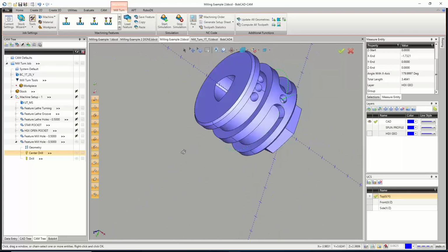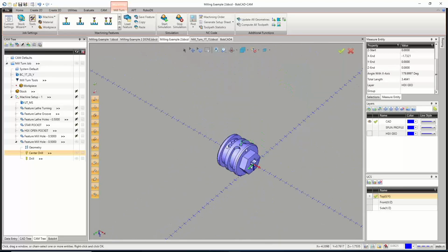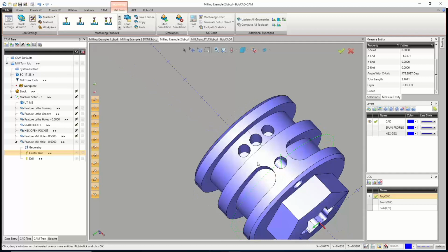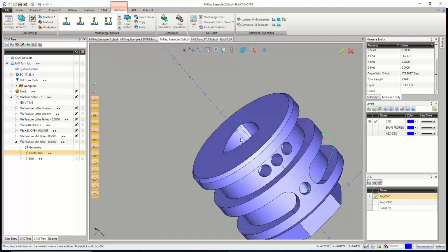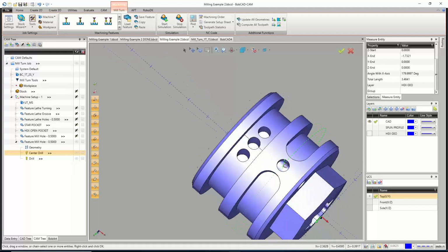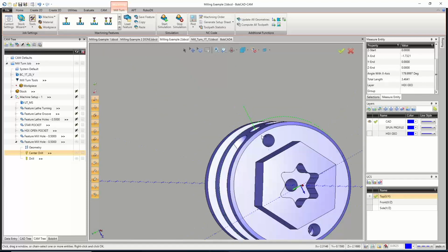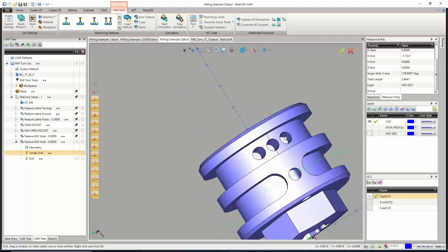That one's pretty easy. Now this other one, this middle one could be drilled with this one, but these other two are not cross drills. They're not pointing towards the center like directly. If with any of these holes that we're drilling now, this top one and this bottom, if we were to go all the way through, we would hit the center line. These ones are all just straight down, so they're normal to kind of there. So it's actually 3 holes.